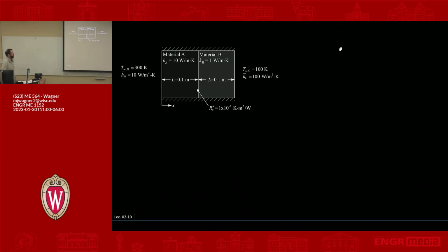First, up at the top, you have a node, and that node corresponds to a temperature, a position at which you want to know the temperature. So that first node is going to be what? This is T infinity H, that's this guy over here. That's the temperature we know. We're given that temperature.